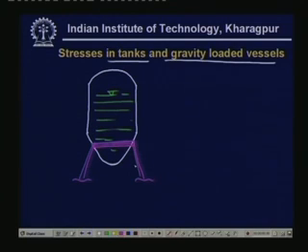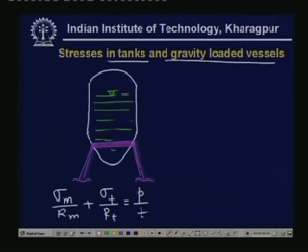In order to get the stress distributions, we will have to use again the formula we have derived. If this is a very thin cylinder, a thin pressure vessel, then one can use this famous membrane stress formula, that is sigma m by Rm plus sigma T by RT is equal to P divided by t. Now, P here is variable. Earlier, in membrane stress in cylinder design, we considered P to be uniform, but now P varies. At point A the pressure is different, at point B somewhat different, and the pressure is 0 at point O. So the pressure varies, and therefore the stress also varies.